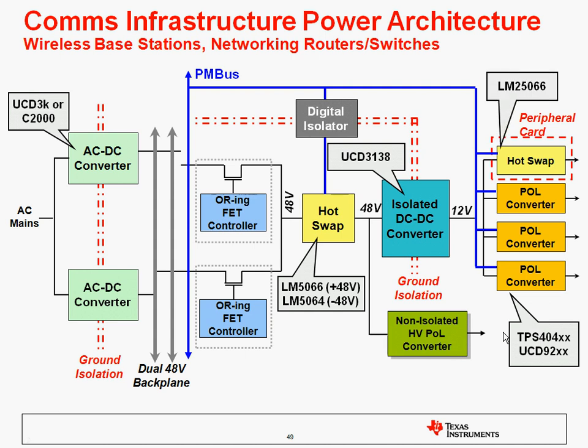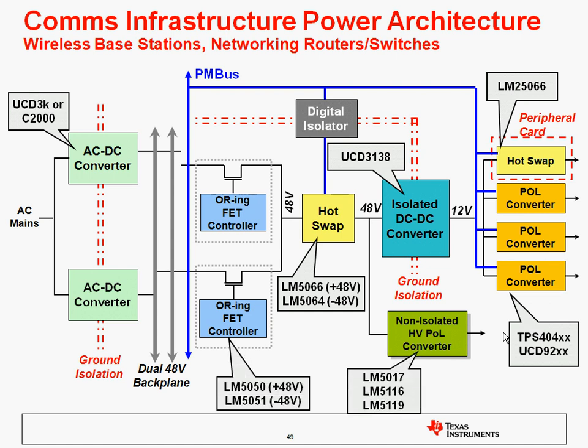And then if there are additional peripheral cards coming into the system, something like the LM25066 can provide hot swap capability as well as power measurement to everything that is on that peripheral card. There are some devices that may not make sense to have the PMBus interface.